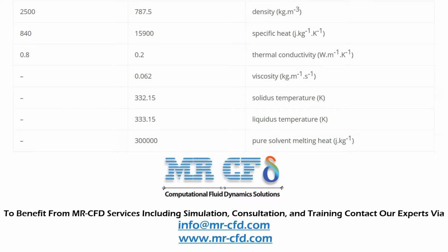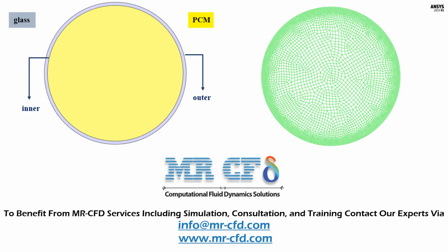Because the simulation process is transient, the simulation is performed in a time interval of 250 minutes with a time step of 600 seconds. The two-dimensional geometry of the model is designed using Design Modeler software. The present model includes a circle with an outer radius and also an inner radius as the circular chamber thickness. Also, the meshing of the model has been done using ANSYS meshing software, and the mesh type is unstructured.